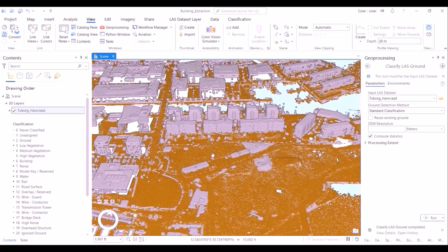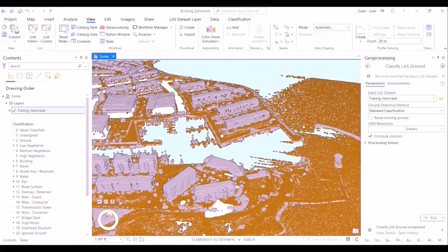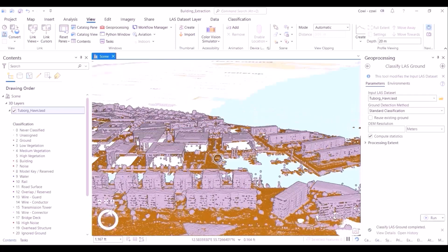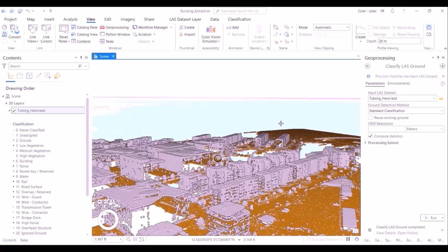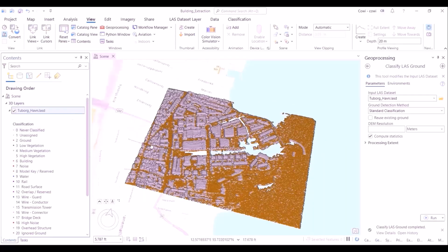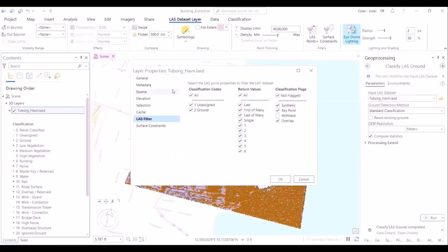By navigating the 3D imagery, the difference between both the classes of pixels is clearly visible. We've done this particular step because we want to eliminate the ground pixel points, whereas the other necessity is we'll use these ground pixel points to create a digital elevation model of the surface.